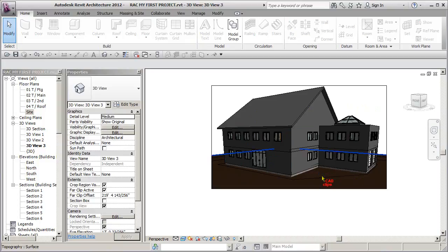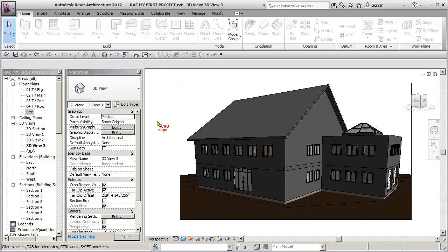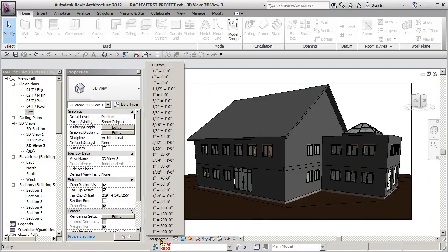As you populate your model with objects, they're going to start showing up here. And if we place this view on a sheet, of course, it's going to show up there. So everything propagates through in Revit. Then you can do overrides if you don't want to see the category or the object per view. Okay, and the other thing is here, we want to pick on this because this is a perspective view. You'll notice there's no scale here.